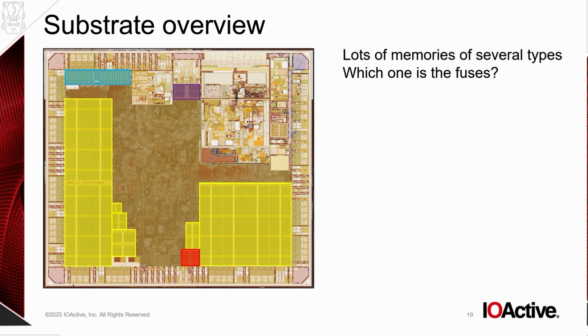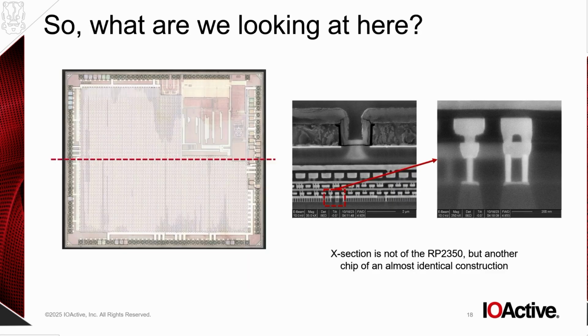So a little bit more background. If we sliced open that fully decapsulated, fully processed chip, this is kind of what a chip looks like in cross-section. It's like a layer cake. You have 8 layers of circuitry, and it's embedded in an insulator material. So everything in that central image there, anything that's bright white, it's conductive, it's copper. And everything that is around it, the darker material, this is just an insulator. So really you can imagine it as almost like a multi-layer PCB.